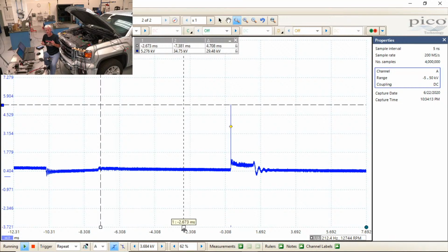And there's nowhere for the spark to go initially, or the electricity to go. Until there's a spark, there's nowhere for current to flow because I've got an air gap. So what happens is that all that energy from that coil collapses and builds up until it has a chance to ionize that gap where the spark plug is. In this case, without any compression, it takes 5,000 volts to ionize that plug gap. And then after it does, it's easy for current to jump that air gap. It aligns all those molecules up like stepping stones, and it can jump across it. So it took 5,000 volts to align all that.